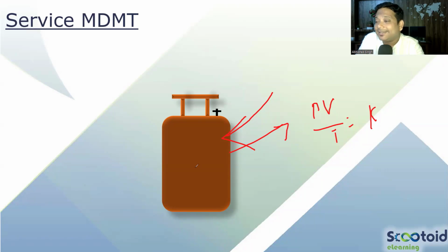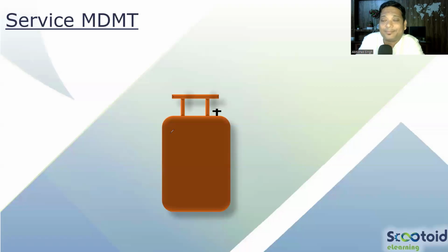Few of you might have already seen that phenomenon occurring. Now you'll ask why we are talking about this phenomenon in a pressure vessel. When can it happen? Is it possible that whatever pressure we have maintained in a pressure vessel, suddenly it gets depressurized? It can happen because of an upset condition. What might that upset condition be? Maybe a pressure safety valve has opened up and it will suddenly depressurize. Leakage is also one. If any leakage happens and the leakage is big enough, with a very high rate of loss, then depressurization will happen.